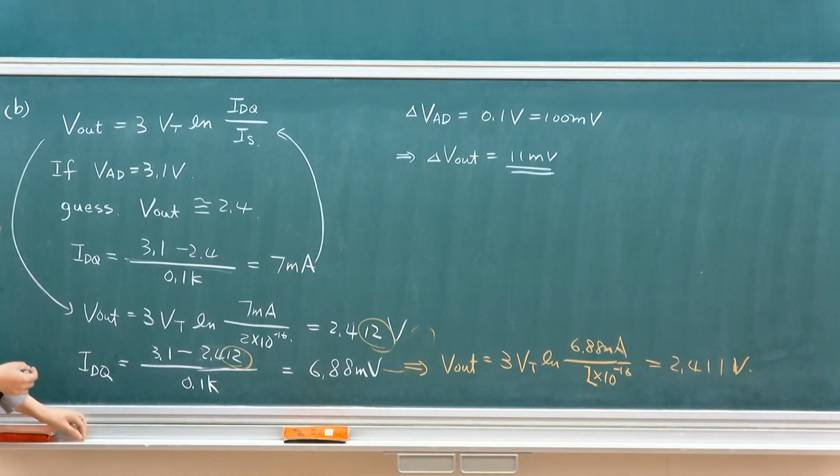Okay? So you will see the power of having a diode circuit, using the exponential characteristic of the diode to achieve that, because it is more stabilized on the voltage front. It could provide different types of current, because the main thing is that you're basically having a different loading current. So even though the current changes a lot, the voltage required to correspond to this current is minimized. Therefore, you will see the less sensitive change. Okay, so this is more like a qualitative description as to what happened, other than just going through the iteration and finding out what happens.